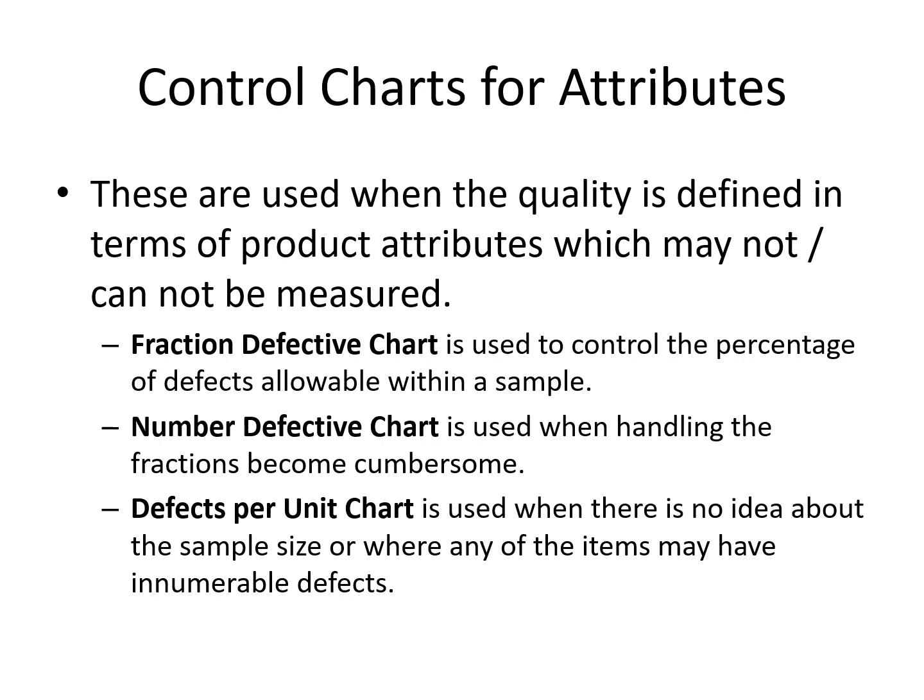When we need to control the defects in such a scenario, we use the defects per unit chart, or the C bar chart. Alternatively, wherever a single unit is to be produced and there could be more than one defect within that unit, there again we use the third chart, the C bar chart or the defects per unit chart. So this is basically about the quality control charts for attributes.